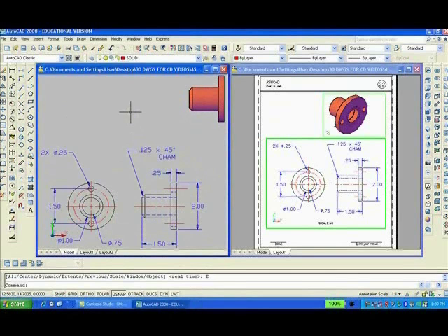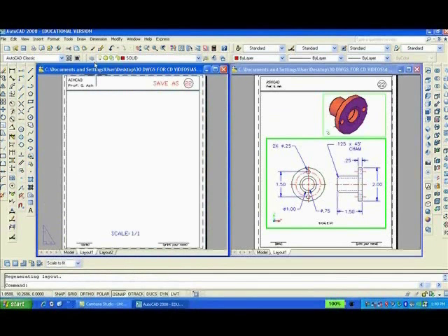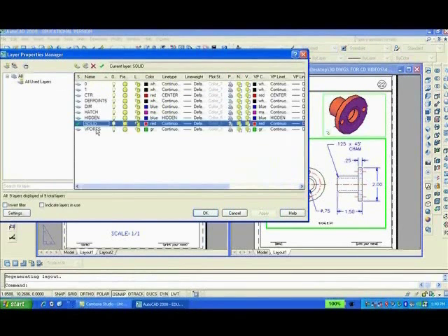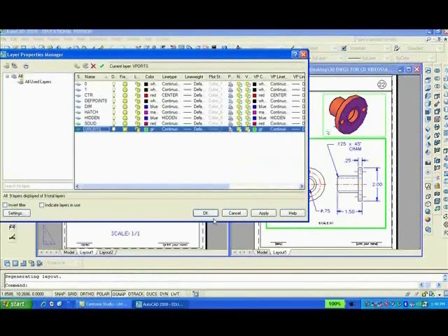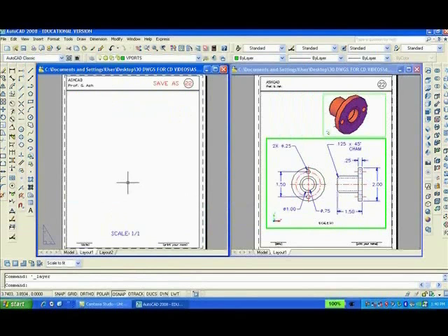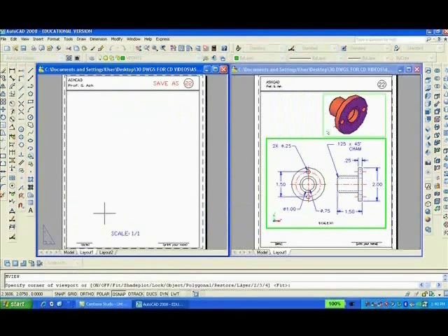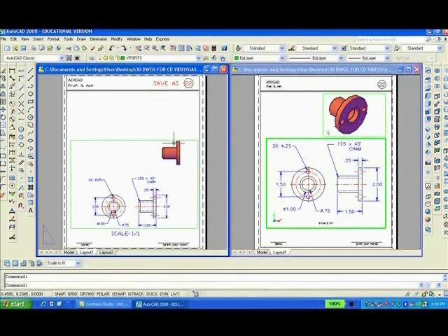And so with the front view, side view, dimension, solid model, we're ready to complete the drawing. So we'll go into paper space layout. We're going to make viewport layer current, and we'll type MV. Pick any point. I think I'll take off the object snap. Hit enter to repeat the command. Do it again.